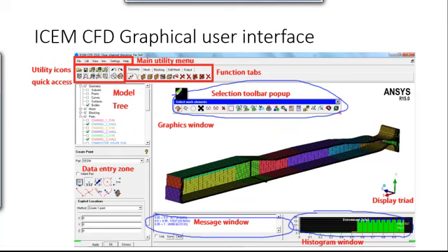So for the blocking, geometry, and the mesh, different toolbars with different options will be there, but the general layout will be similar. You can see over here this is basically a mesh toolbar, which is visible from here. It's the surface mesh, volume mesh, line mesh, and the point mesh. So here you can select the different options. You can select only surface mesh, you can only select the volume mesh.